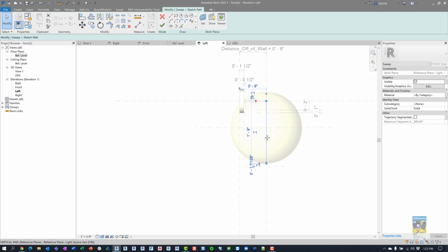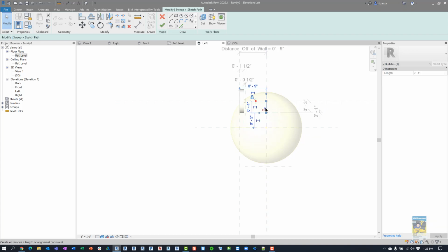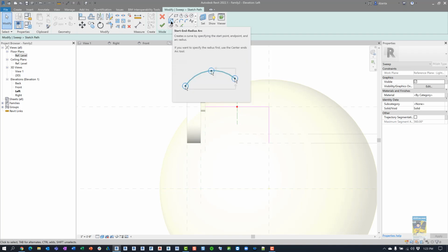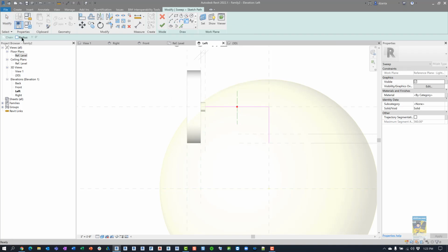This one here we'll pull up as far as we need, which is going to be, in this case, maybe here at the most. Okay. Now we do need this to have a nice curve. So we can do this one. Fillet corner with a radius, and we'll just do 1/2 inch. And let's see how well that comes out. That's pretty tiny. Let's change this. Let's make this 2 inches. And try that again. There, that's better.